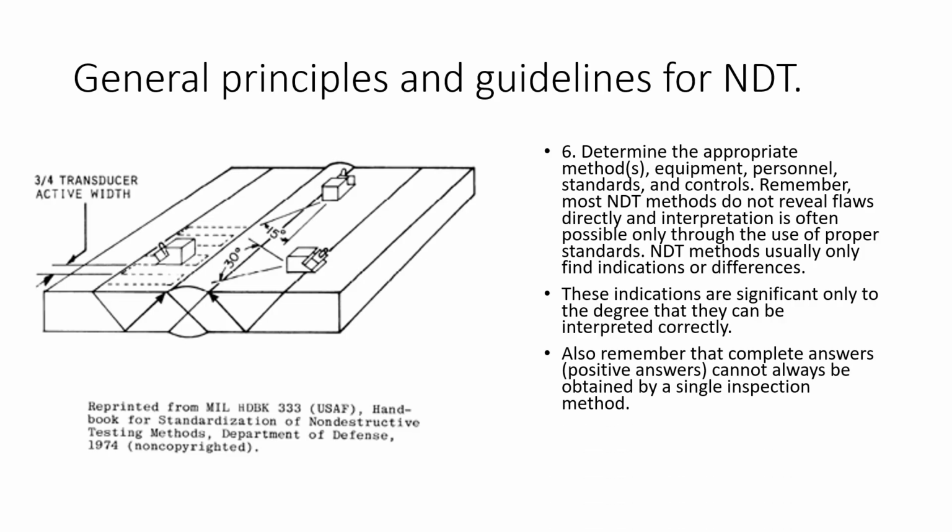A lot of times we need to use 2 inspection methods to figure out what's going on. We're going to have to use visual inspection and mag particle, or sometimes we're going to need 2 because one method might not get us to where we need to be. Or we're using visual testing and then we see something that's a little weird, and then we use magnetic particle testing to really zero in and find out if there is a defect or a discontinuity that is actually a rejectable defect and makes that part unusable. A lot of times we need 2 methods to get a complete analysis of a part.